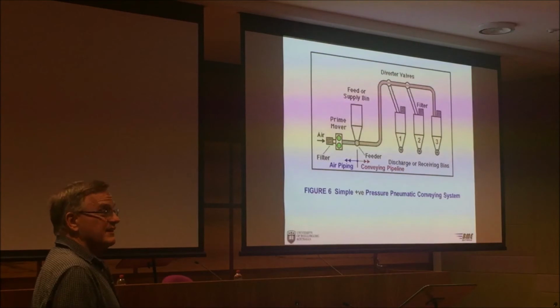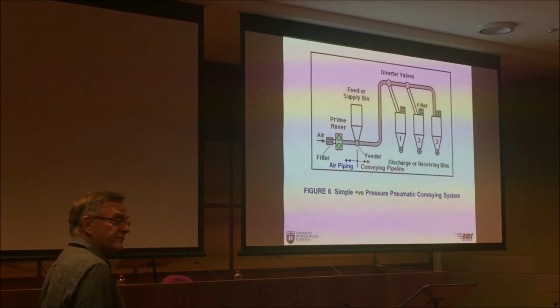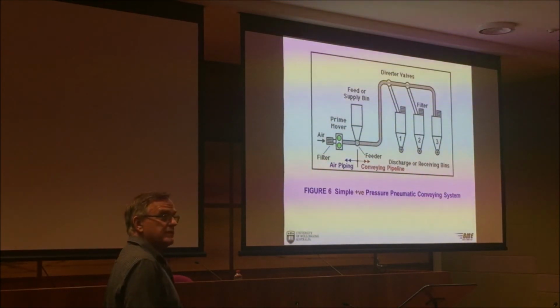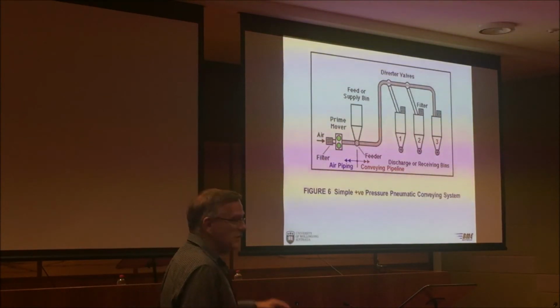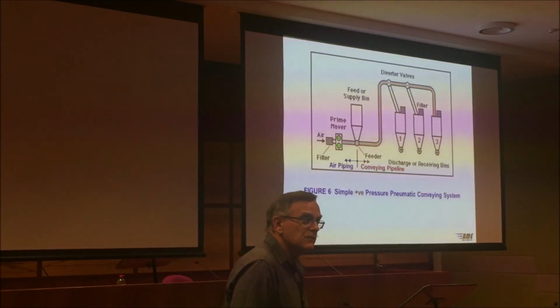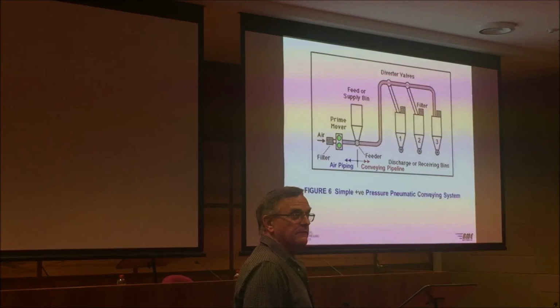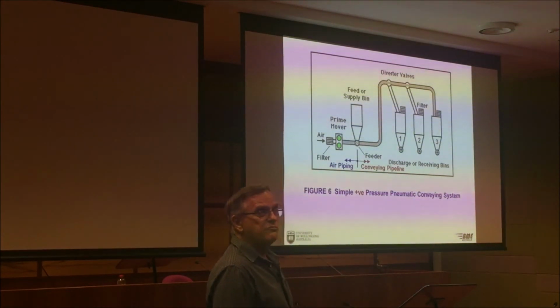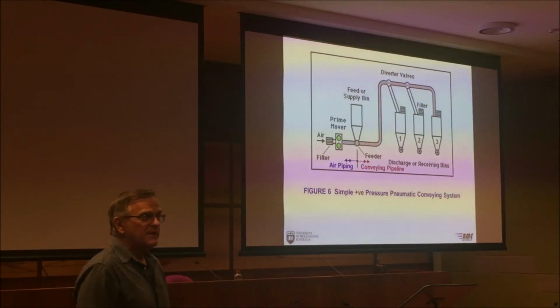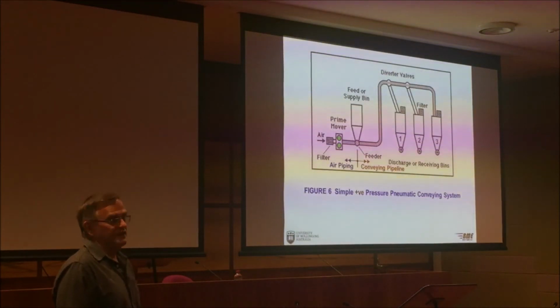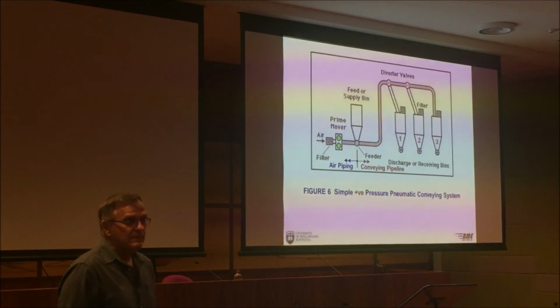And surprisingly, based on some work we've done in India, a lot of the power stations there with their ash handling systems, a lot of the engineers have overlooked the losses due to the air piping. And some systems are 200 or 300 metres long. That's a few kilopascals, 50 kPa loss across the air piping system.